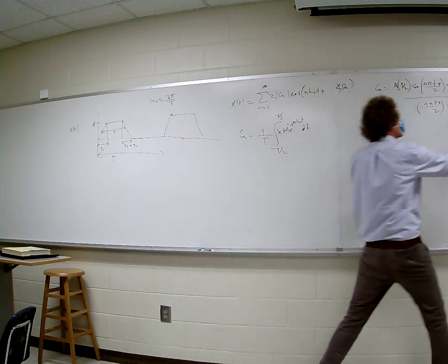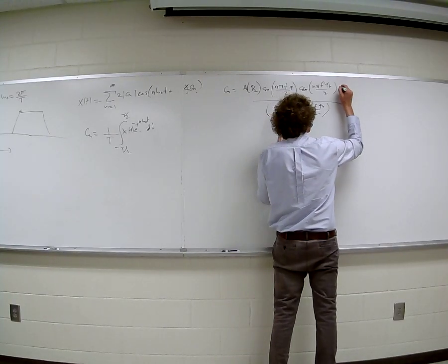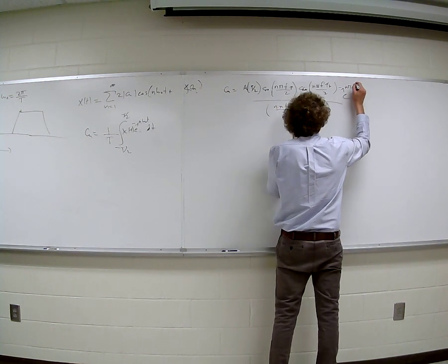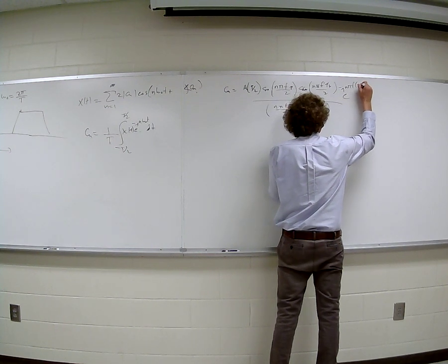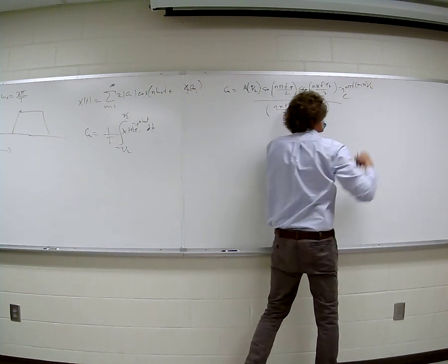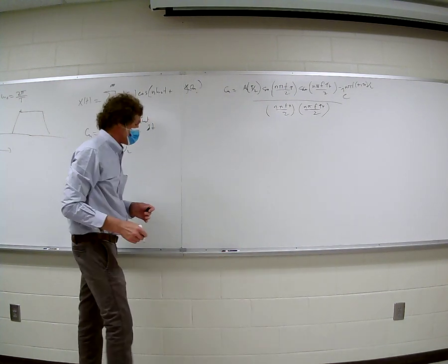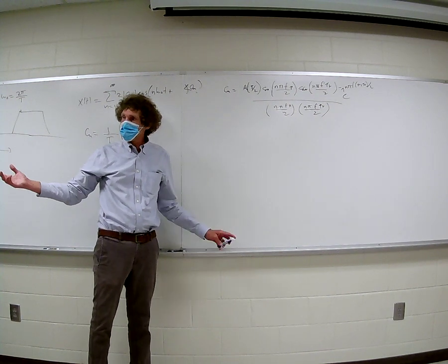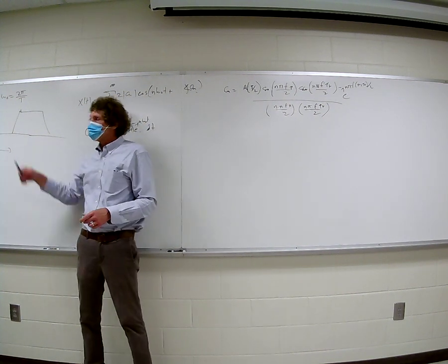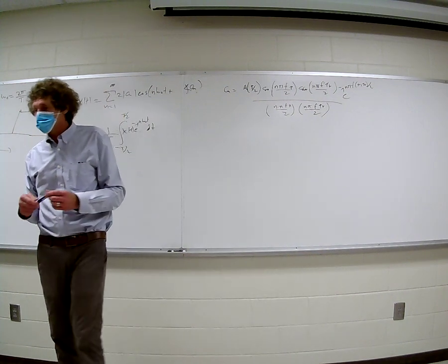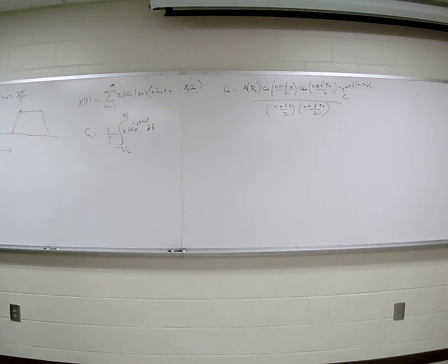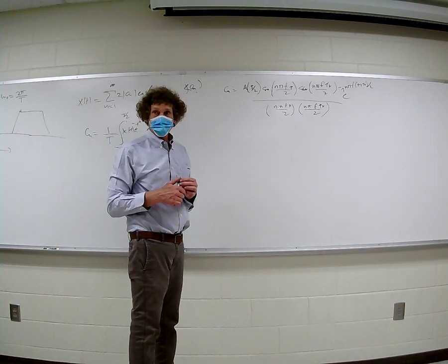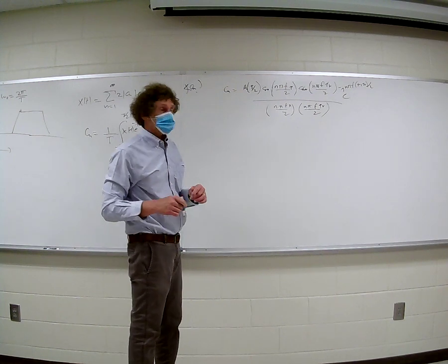And there's also a phase term, e to the minus j n pi f times tau plus tau rise over 2. The phase term you can ignore. That's what you came down to, if you recall. Now I'm just putting this up here so everybody has a point of reference. You all remember that? We proved it by doing double derivatives, getting the Fourier series of the derivative series where we had impulses, and then reversing the procedure to get c of n by dividing by j n omega naught squared, right? All remember that? All right, I'm trying to get there.